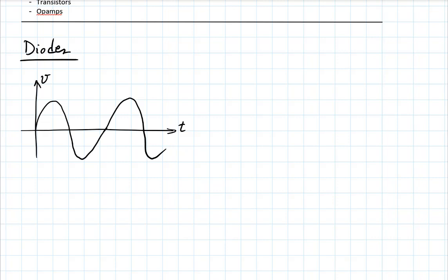So I really like that. The suggestion here is we have this signal that's half positive, half negative in time. And because of that, the average is 0. But what if I could somehow get rid of, let's say, the negative parts? Then if I have left only the top part, the positive part, the average of that, I think you would agree, is some positive value, right? If you take the integral over this area, or over this time, and you get the area, well, that's a positive value. So if I could somehow throw away the negative half.